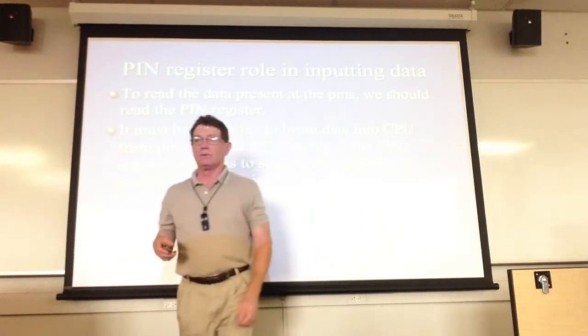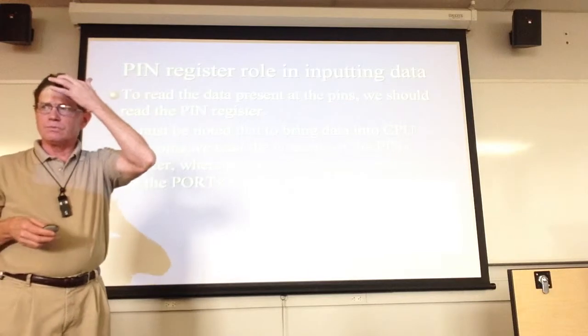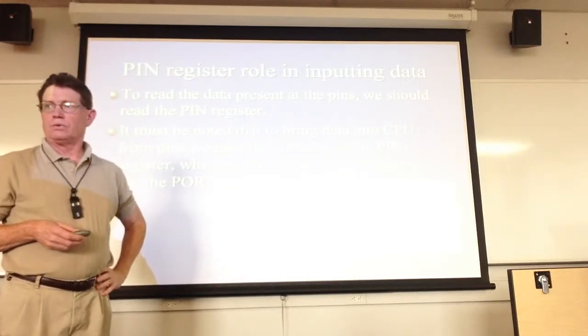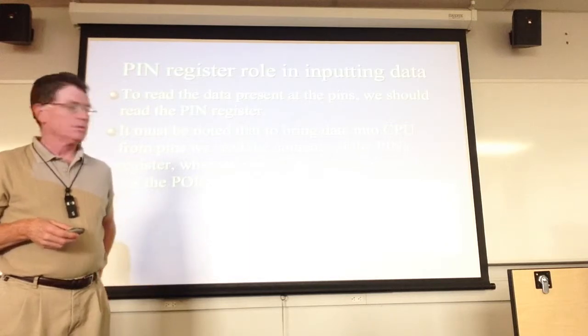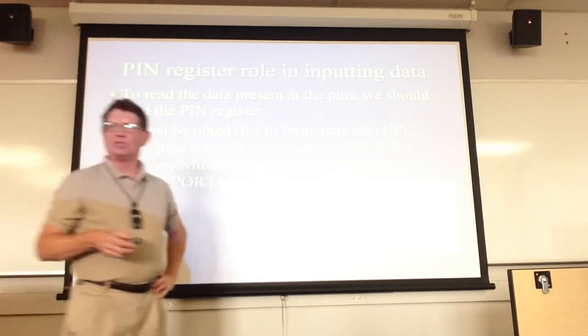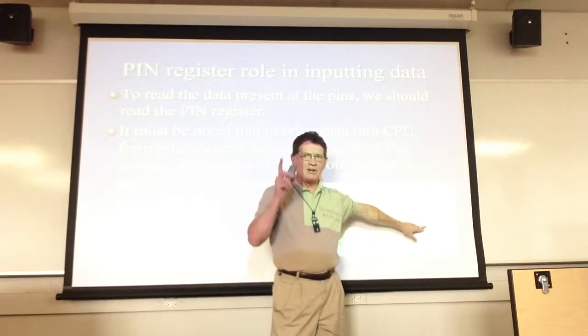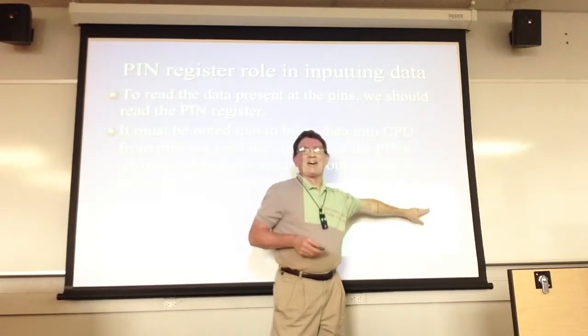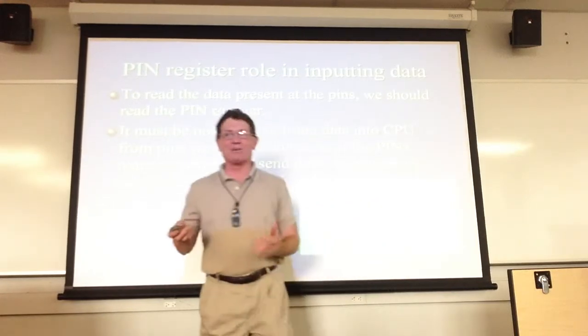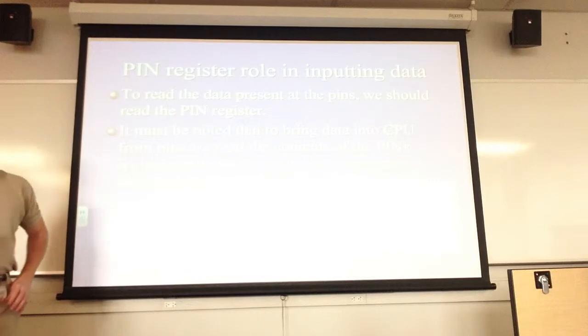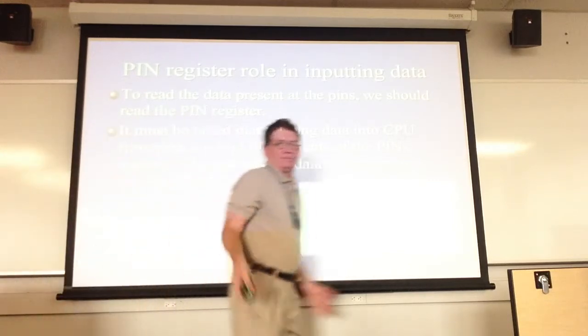Is there another switch in the pin in line? Or I guess the question is, if we set it as an output port, will the pin register then follow whatever we set to the port register? Yeah, probably should. I would think so, because whatever you're writing here is going to appear here. But then again, remember, I'm writing out. I'm not reading in, because the data direction register is set up. I was just curious if I were to set the port and then read the pin, if they were to be the same. Yeah. Okay.